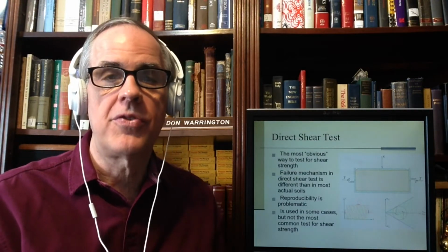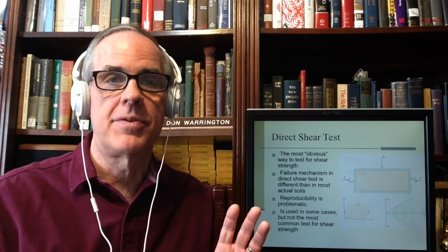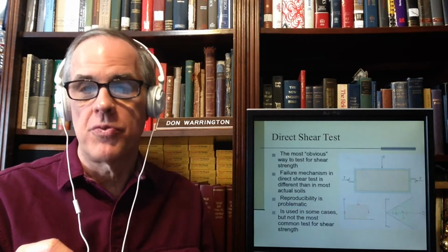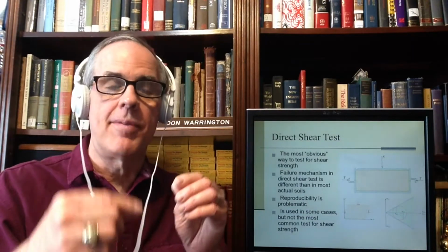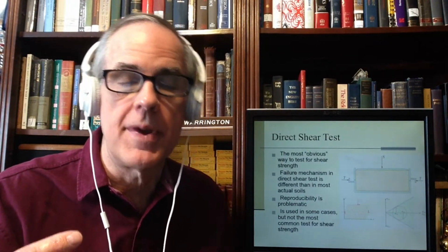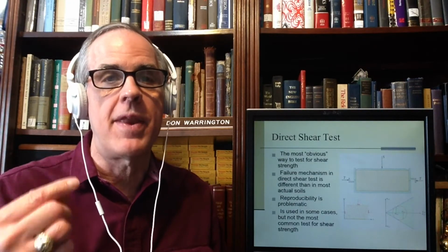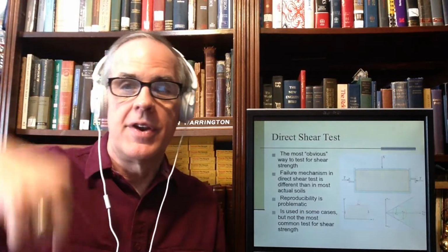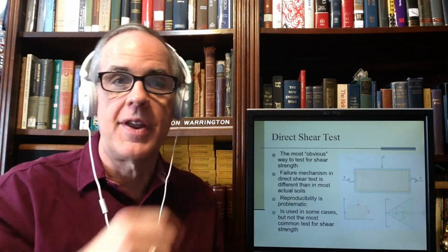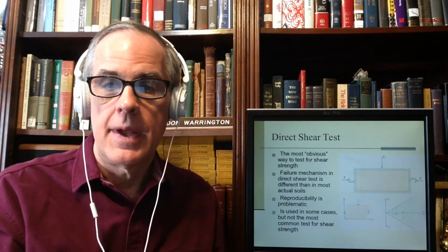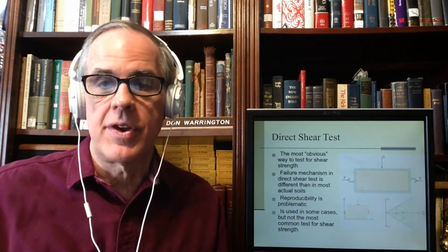So basically what you do for soils, you construct a box, and you split the box in half, and you push one half of the box one way and the other half the other way. Because this is a granular soil, and its strength is dependent upon the pressure it's under, you have to have a normal force, which you see by N, on top of it. And you can measure the shear strength.